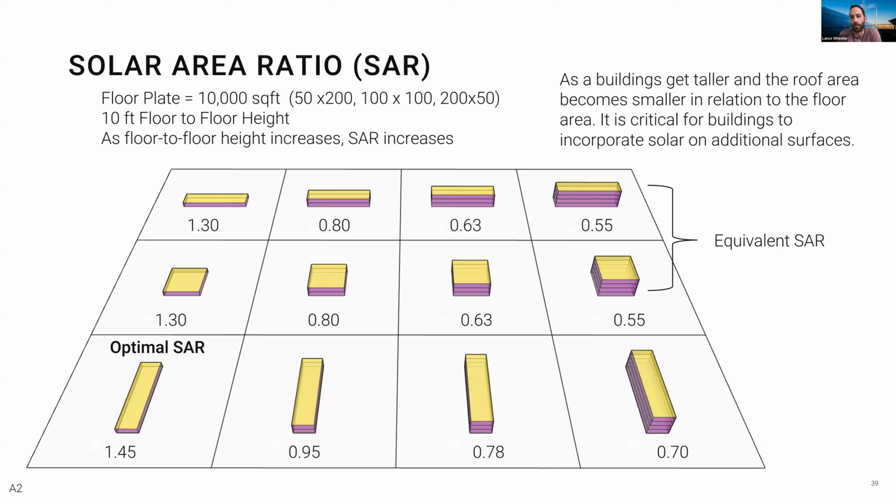And it's really how the rest of that panel is designed. You can design infrared reflecting coatings, things like low emissivity coatings on your panels, to prevent some of this added load that might come along with putting black things on the side of your building. But it's all pointing towards the fact that it is a fairly new space for folks. I think you will be heating your building more than you usually would, but there are ways around it, ways to prevent it. I see Chris has something to jump in with.